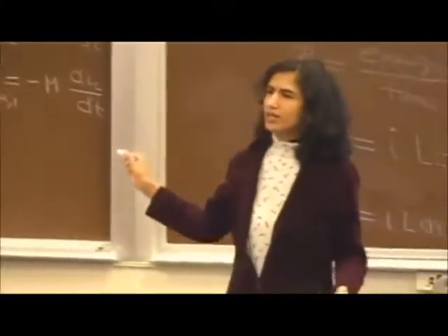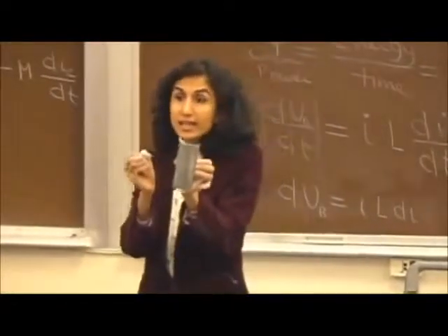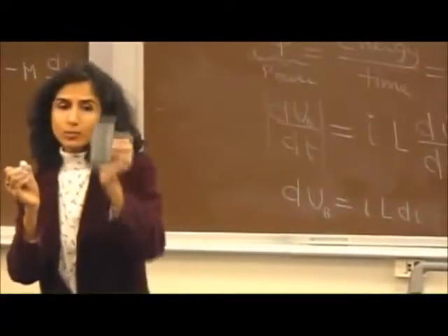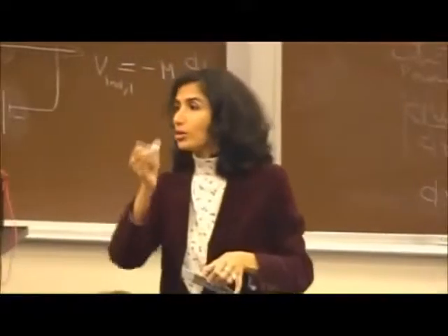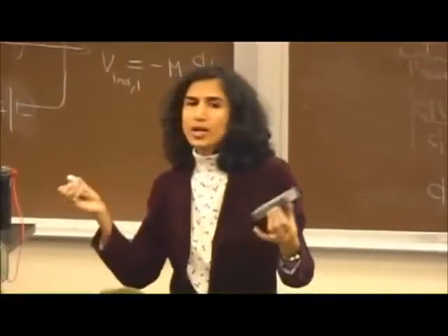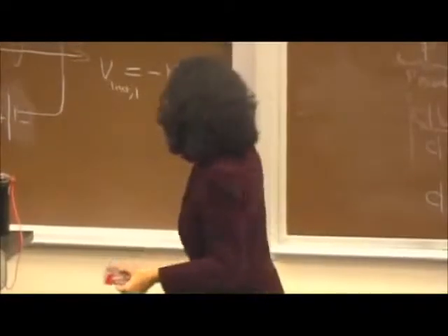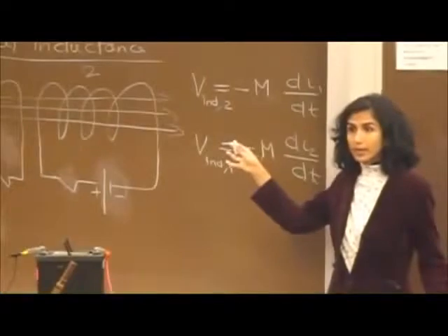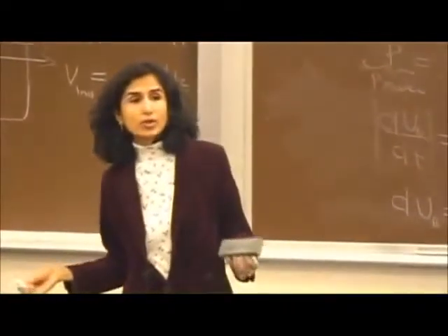But let me just talk about it here, because it's a very nice application of this fact that if two coils are sitting next to each other, and you are changing the flux through one coil, and it's also looping through the other one, you are inducing an EMF in the other one. This phenomenon of mutual inductance. And do you see that this is due to Faraday's law? We are really talking Faraday's law, right? This particular thing is really useful for making transformers.